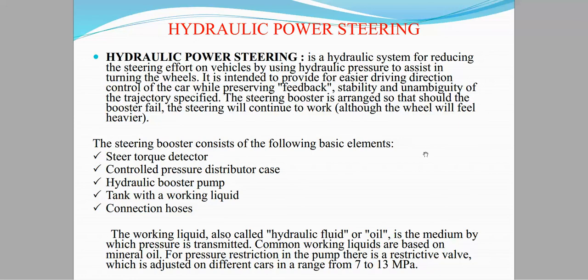The steering booster is arranged so that should the booster fail, the steering will continue to work. The steering booster consists of elements like a steering torque detector, controlled pressure distributor case, hydraulic boost pump, tank with working liquid, then connected hoses.